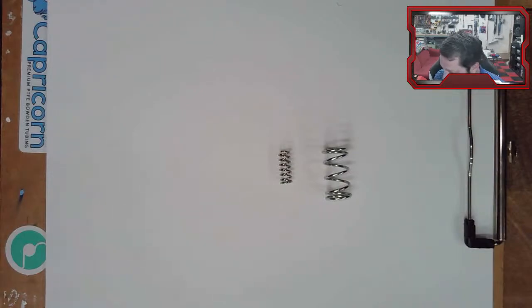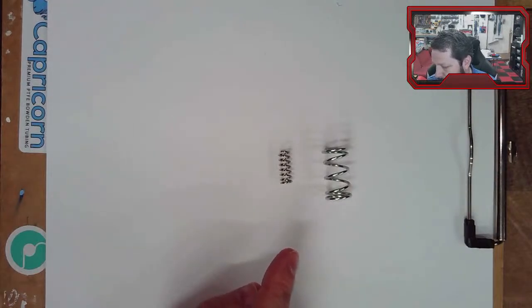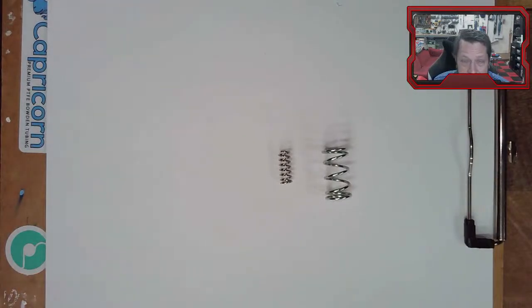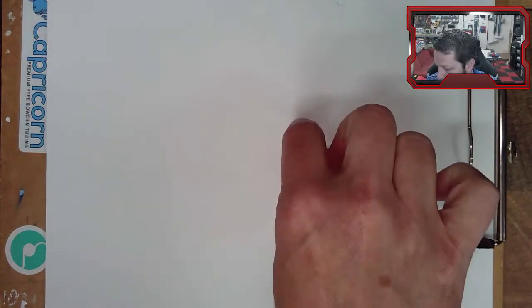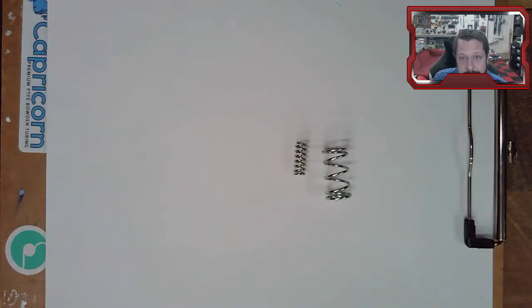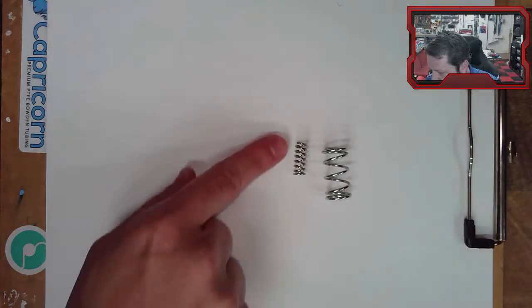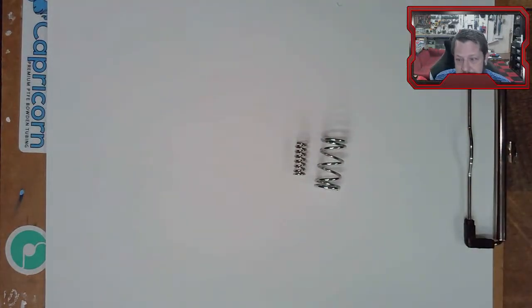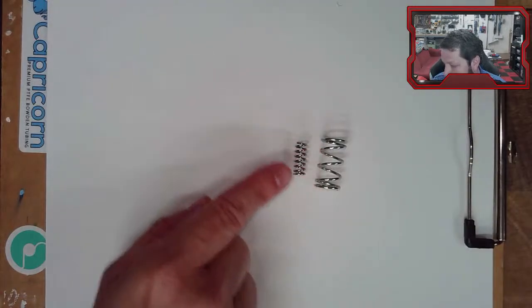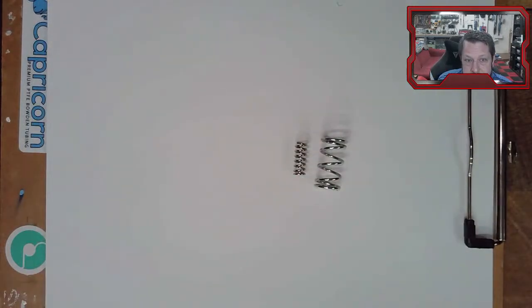coil springs. So what we're interested in is some springs have to operate, close and open at high speeds. I'm thinking sort of the springs in a valve train in an engine, a car engine or a truck engine. They could need to operate by being squeezed over and over really quickly. And if you get the wrong frequency of that, if it's too high a frequency, you'll enter the fundamental frequency of this spring, depending on its geometry.